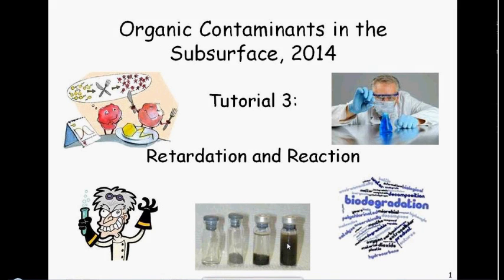And it usually takes 24 to 72 hours to reach equilibrium. You would then analyze or centrifuge the sediment away and analyze the water. So that would determine how much of the chemical stayed in the water. You knew how much chemical you added by knowing the concentration in that original water. The difference then is how much mass went onto the solid. So that gives you your KD value.